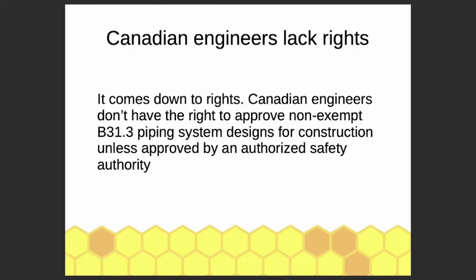So they have a quality system that was audited by the ASME National Board, and they are now permitted to build vessels. However, an ASME authorized inspector from outside, a third party, someone who doesn't necessarily work for the company but could work for the company but is separated and objective, has to inspect the vessel.